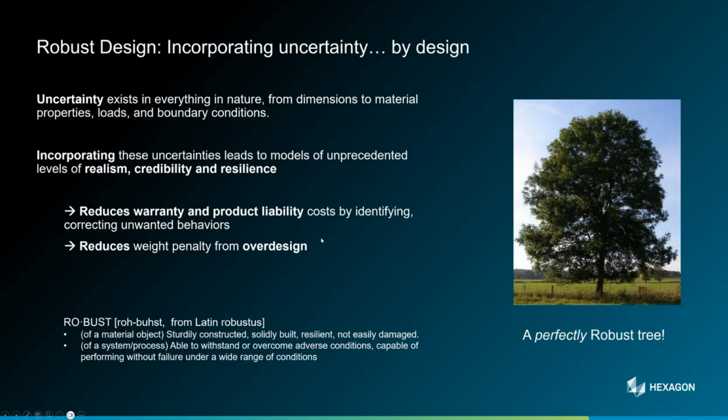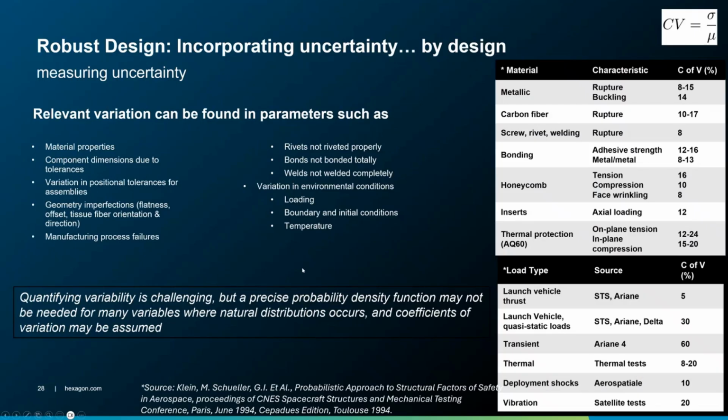and it's not necessary. So with this brief introduction to the problem, you might spot the devil immediately. You say, okay, but I don't know the variability, right? How do you define variability in my components? So first of all, the non-dimensional standard to define variability is the coefficient of variation, which is the standard deviation divided by the mean value.